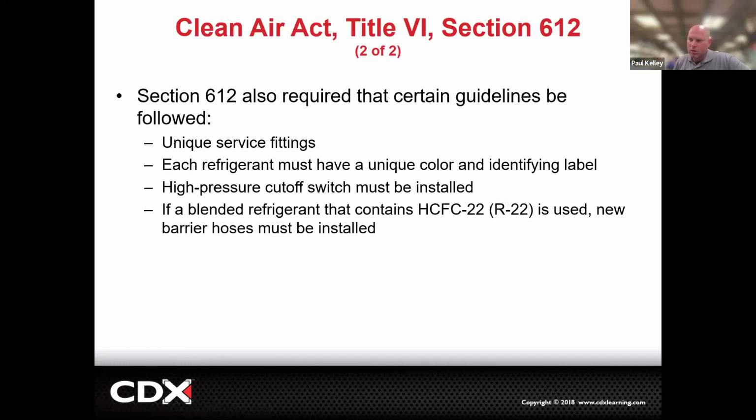Back in the day with R12, the hoses were a little more porous. A barrier hose is a very tight molecule hose, and R12 was kind of a larger molecule. It wouldn't really get out of those, but R22, R134A, and 1234yf are all smaller, so they will actually have a tendency to leak more.